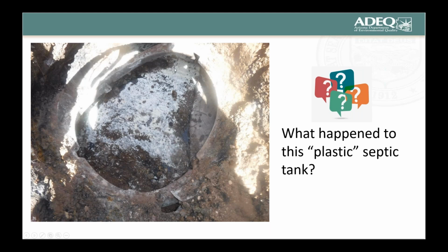I don't know, this picture doesn't give me enough picture of how far down this is, but if everything gets really wet and saturated, your dead loads could be pretty significant. If the bedding of this tank was improper, the side loads could move in, because a flexible tank needs uniform support along the side or it will collapse.